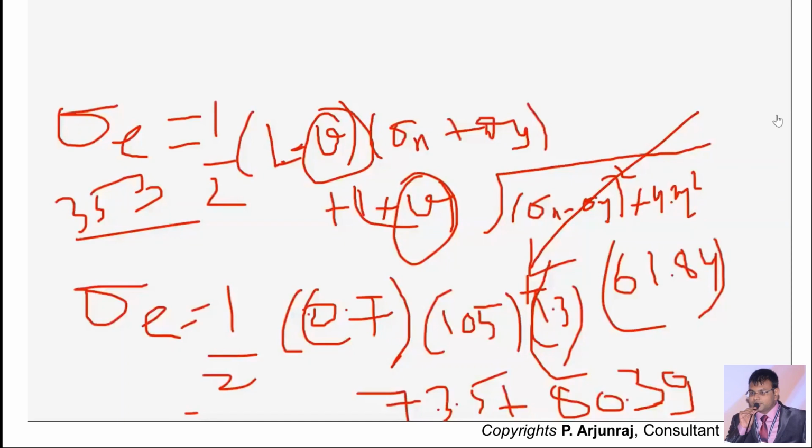And say for example, when you're taking polymer foams, the Poisson ratio will be very near to zero, as the cells are going to get collapsed during the compression. Normally the solid material will have a Poisson ratio between 0.2 to 0.3, and